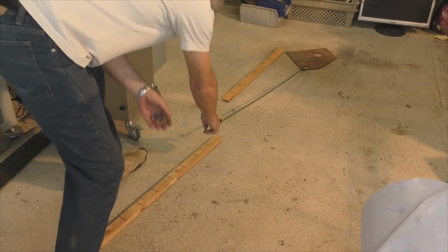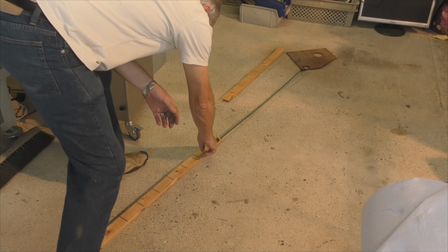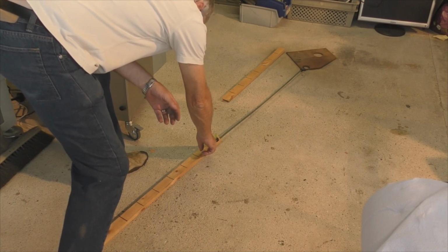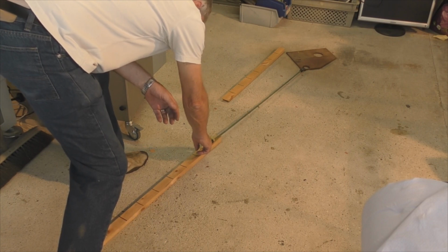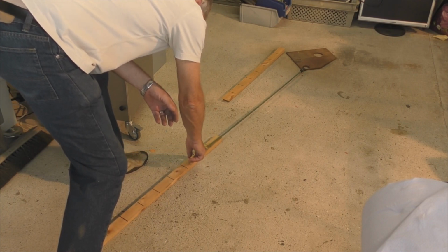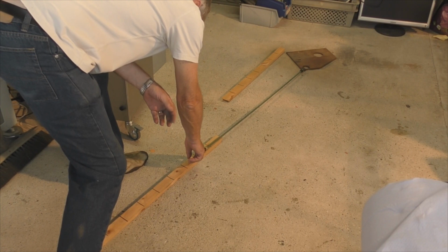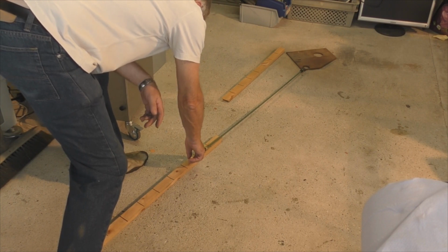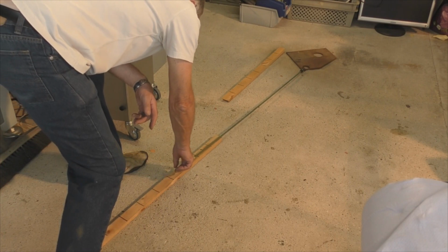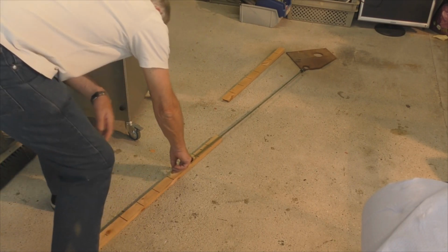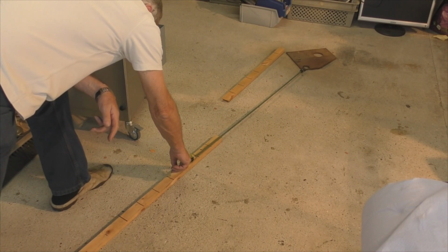So the first thing that I'm going to do is I'm going to start at 0. And I'm going to say, right, let's put one step onto the stepper motor. Yeah, we've moved a step. What's happened to the load? Nothing. Let's move another step. What's happened to the load? Nothing. Let's do another step.